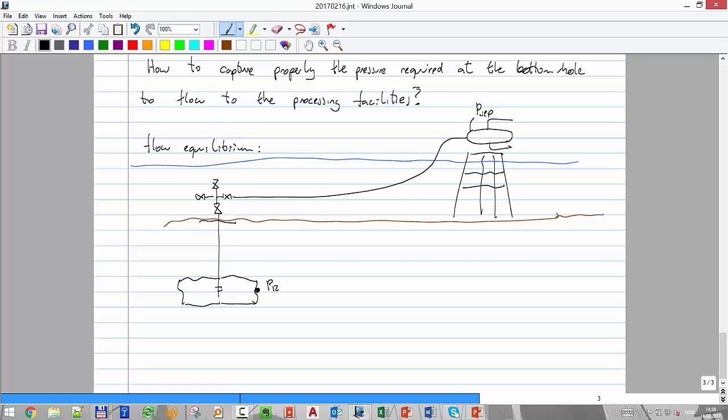I think we talked about it before. What two elements does the separator have? Two controllers. Level controller and pressure controller, we had that discussion before, right? So it doesn't matter what comes to that separator, it will try to adjust the two valves such that you have all the time the same pressure. So those are the two limits, or what I call the bounds, of the rest of the system that I want to study. That clear? Okay.